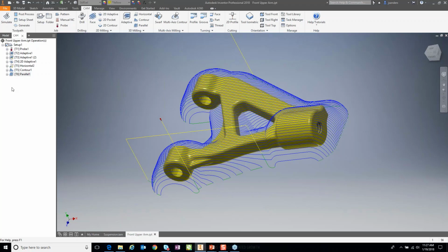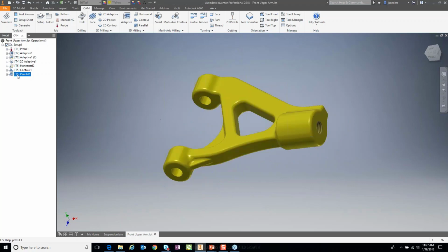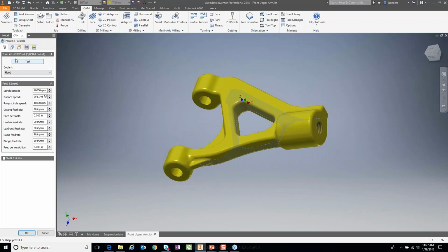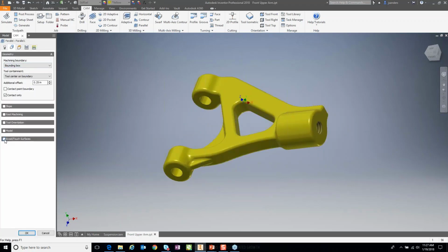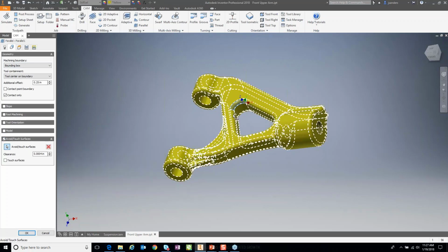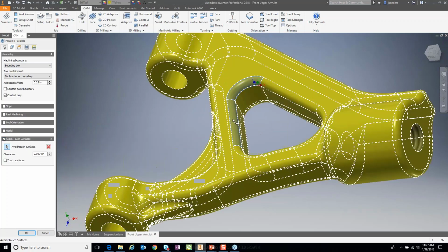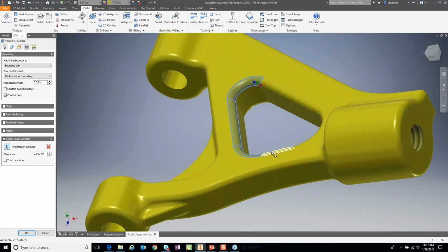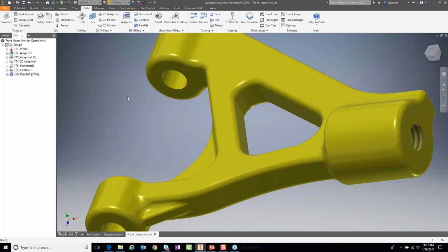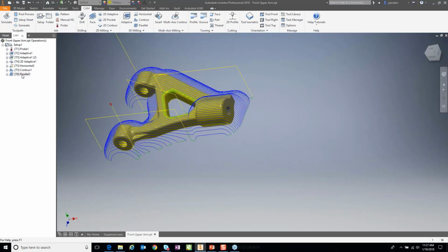We also have the situation where the tool path drops into that area. And again, we can go in and have the software avoid those regions simply by going in and picking those. Zoom in a little bit here to make it easier to pick. So standard picking functionality that you'd be used to on the CAD side of the software. The resulting tool path now stays out of those regions exactly like we intend.